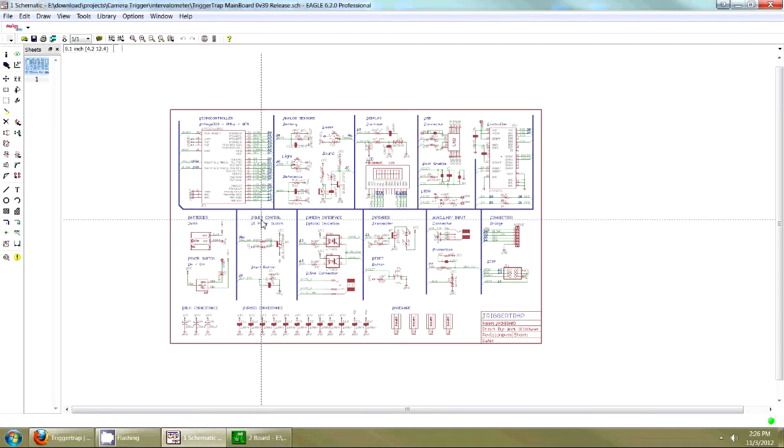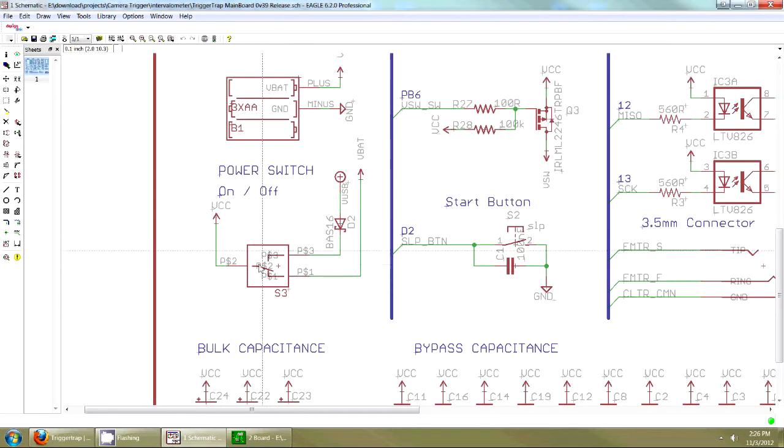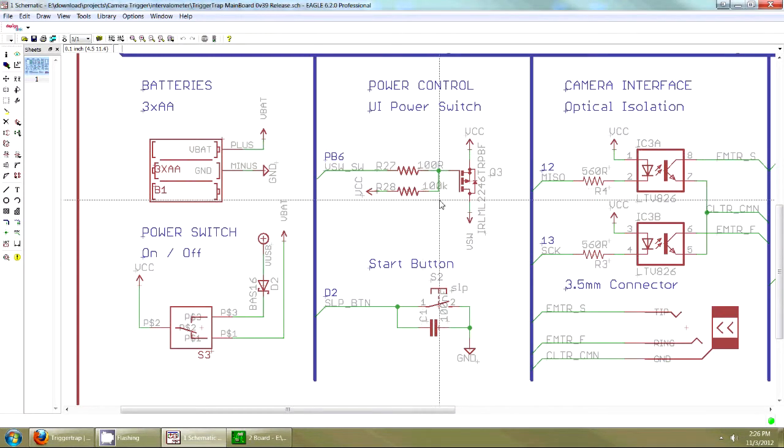The bottom schematic looks a lot like the TT version K Shield with some notable differences. Mainly as a result of being battery powered, there's a physical power switch down here, and to the right of that we have a P-channel MOSFET here that's actually used to cut power to unnecessary components during time lapse. This allows for continual 5-month plus running time for time-lapse sequences.